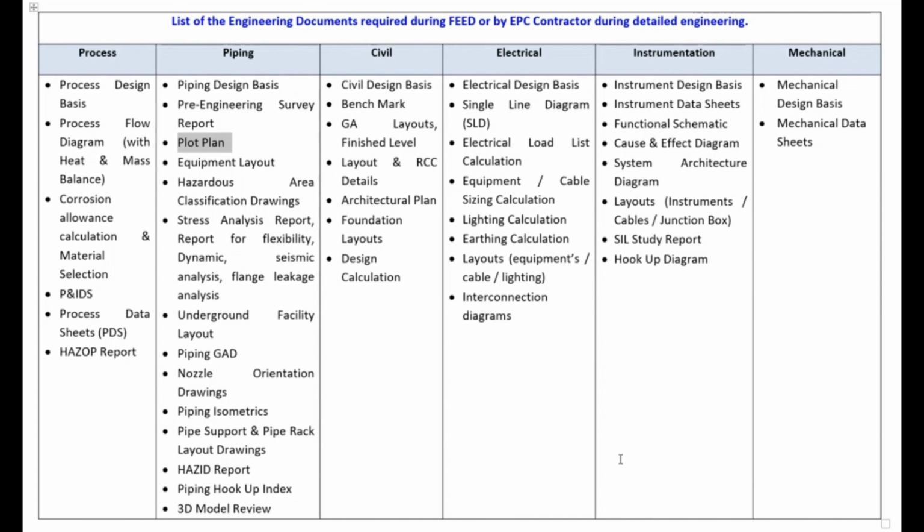The plot plan is developed based on the bill of quantities, what we are going to have in our plant, everything, what are the main equipments, areas we are going to have. While developing the plot plan, when we review it we'll understand that in more detail, but the basic idea is like you cannot make your office next to the compressor area, okay?